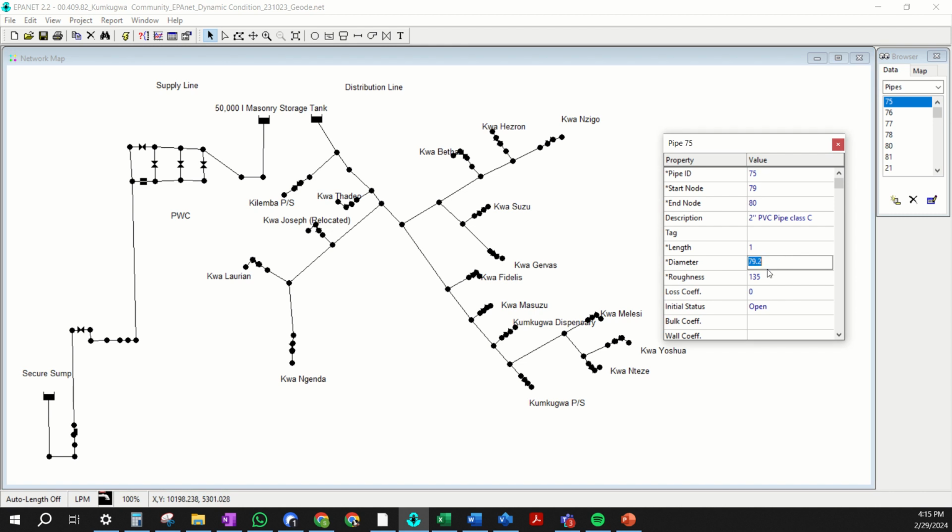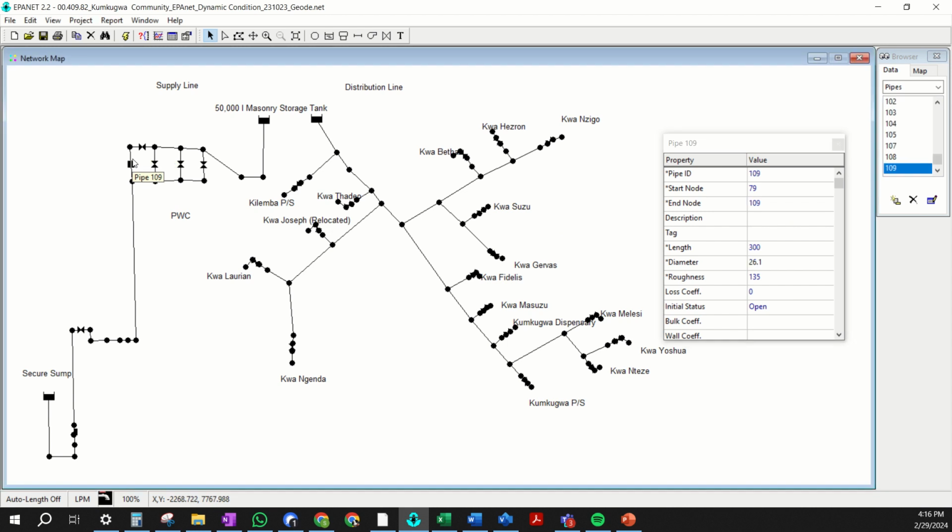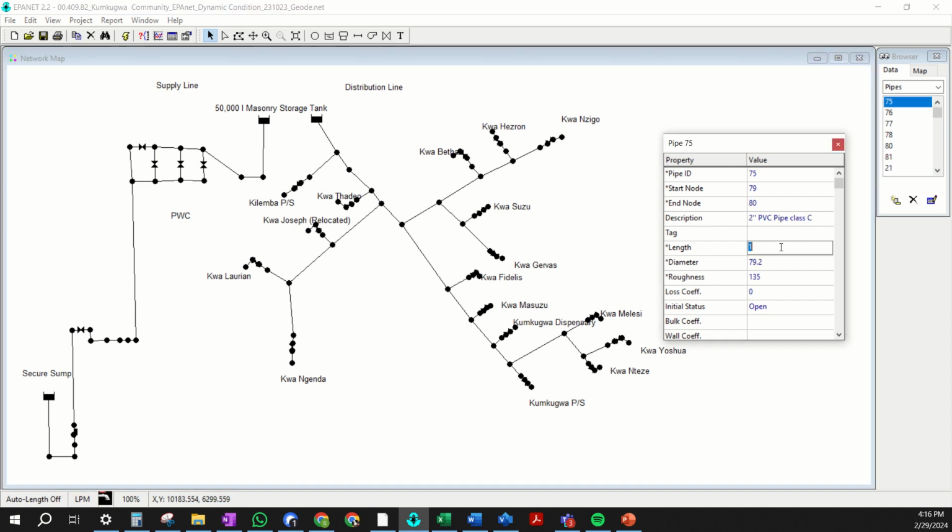So I'll use 3-inch PVC. I would not go all the way down to 2-inch. You could use 2.5 since the flow is divided. But if you need 3-inch piping in your pipeline, then you need 3-inch piping inside your treatment house. So we'll make all the piping inside here to be 3-inch. These are 0.5 meter spacing.